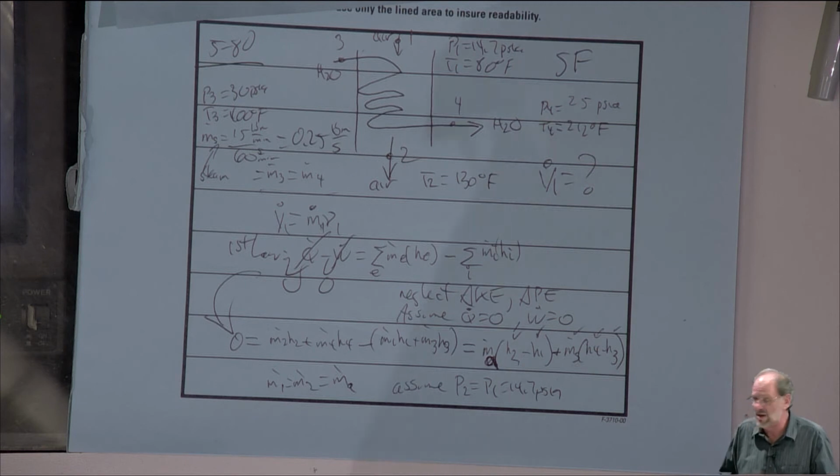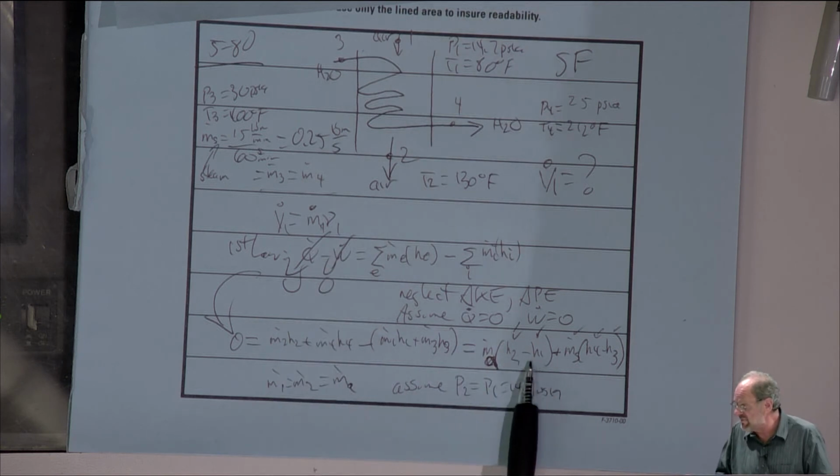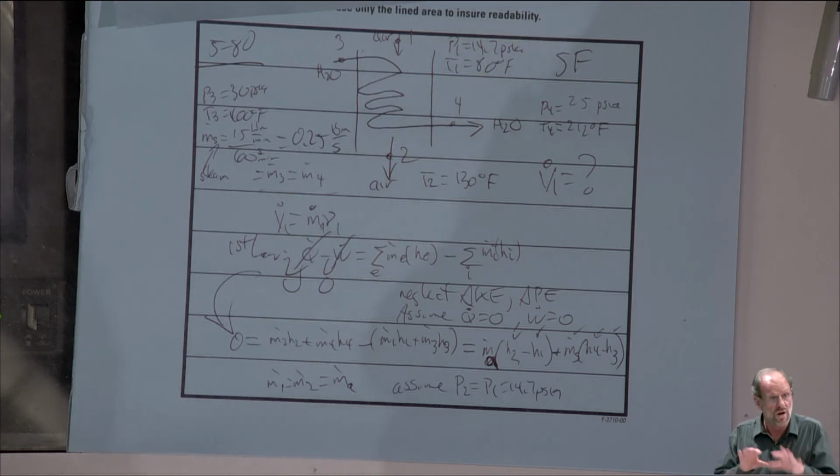It's a specific volume of air we need, and air is a gas, and we're going to have to assume that it's an ideal gas, not just to solve the ideal gas equation of state, but also for the enthalpy change term. We don't have the ability to use air tables. Now, I will make a note here. Table A17 in your textbook are air tables, but we're not going to actually use those air tables until we get into ME302. We're just always going to assume that air, like any other gas, is treated as an ideal gas. We'll use the ideal gas equation of state. We'll use specific heats at constant pressure, constant volume, whichever is appropriate. But don't use table A17.